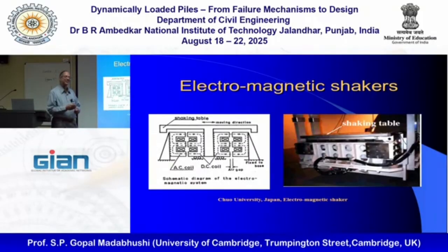And that is really where the Japanese, even they found they couldn't shake big models on that electromagnetic shaker. Otherwise, it works very easily, and you can buy an electromagnet probably in Jalandhar market. They are everywhere, right? Electromagnets are so common, so it's not hard to get one. But on a centrifuge, we need to get the current, basically power, voltage, and current onto them.